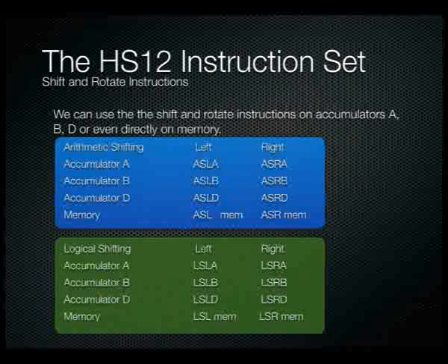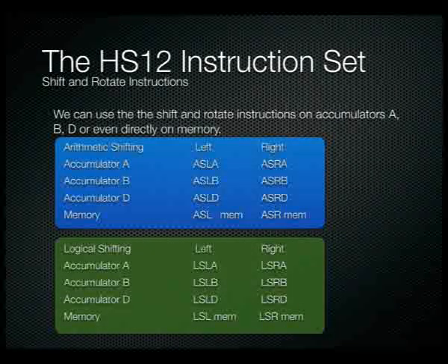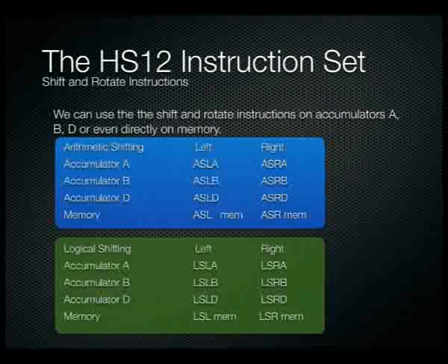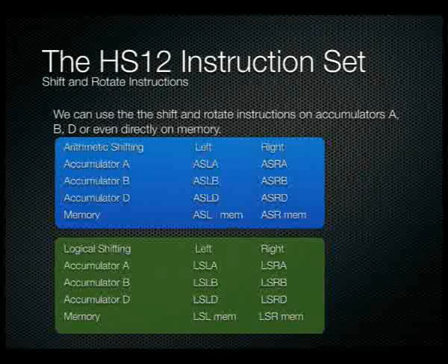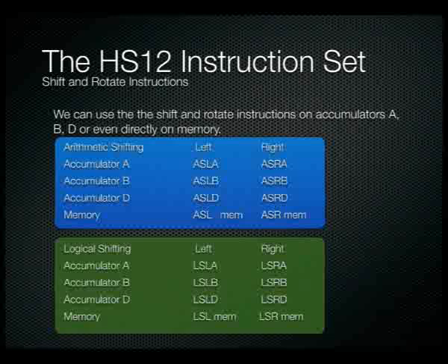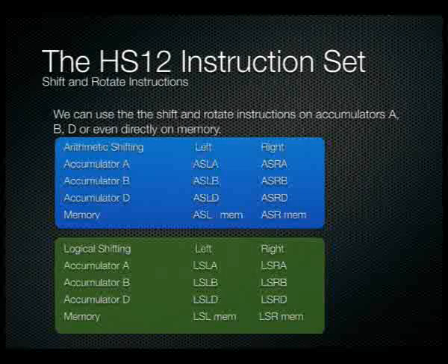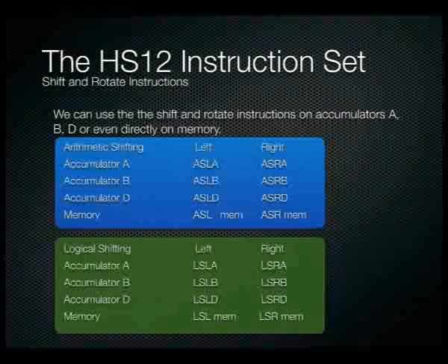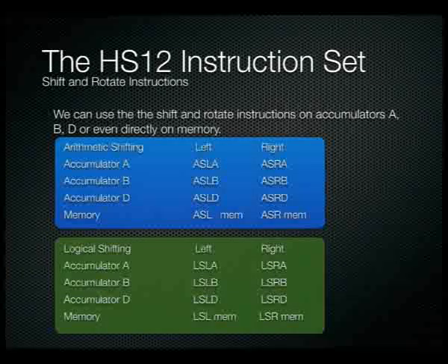Okay, so another operation that we like to do inside the processor, we like to move data around inside the register. So we actually like to shift it left or shift it right by a single bit at a time. The beauty of shifting data left or right is that we can, if we're connected to a particular I/O device, we can strobe a particular line at a particular time simply by using rotates.